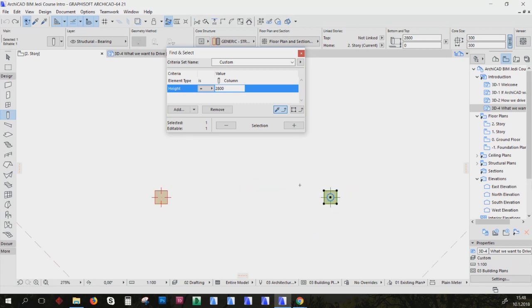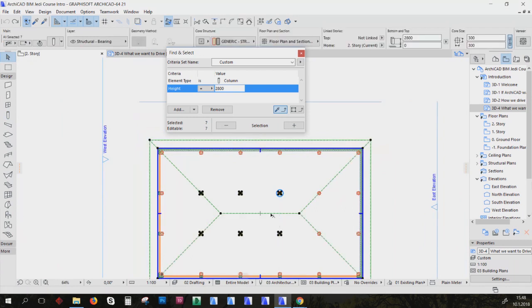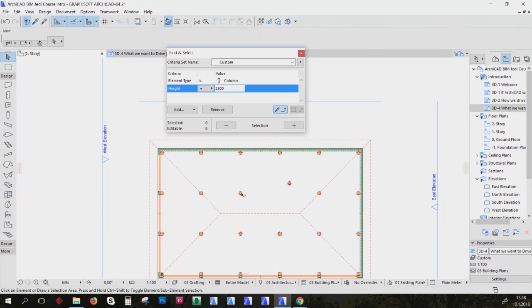Then there's the grouping one, for grabbing a whole lot of things. Control G will put them in a group, so anything you do to them, they'll move together. If they're in a group and you only want to change one of them, you can turn grouping off with Alt-G, change that one, and then turn grouping back on with Alt-G. They all stay the same and will all act as they did before, still as a group.